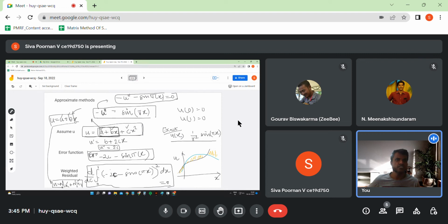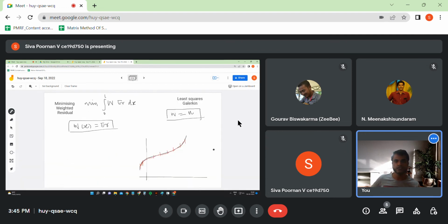Okay, and how to convert this, we have seen it before, we have discussed it already. Where n1 and n2 we call shape functions, they give the interpolation between both the displacement points, right? Fine, so this is what I wanted to say: in finite element, we are trying to find approximated answers by breaking a bigger domain into smaller domains, and in each domain we usually fit a linear curve. It is also possible to have a quadratic variation and so on, but we usually stick to linear approximations, because those are easier to solve using computer algorithms.